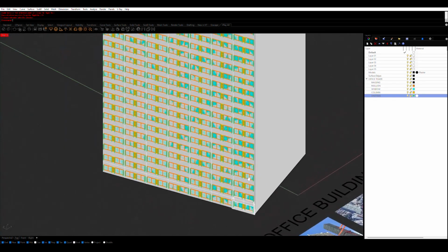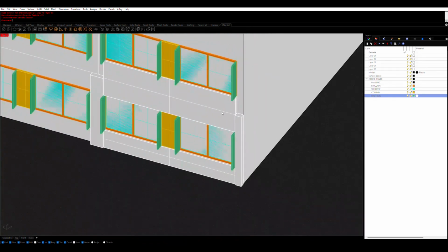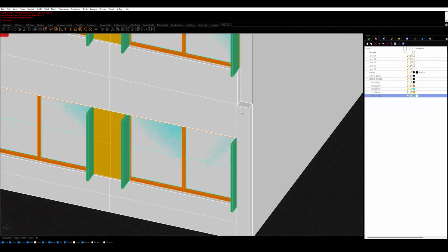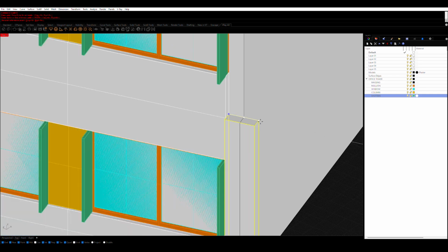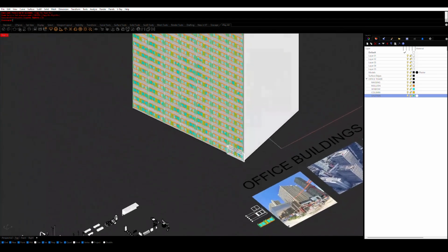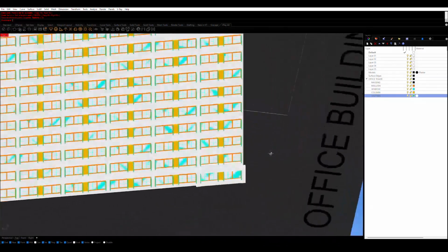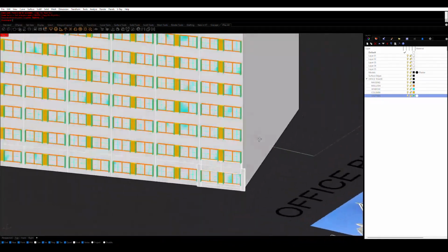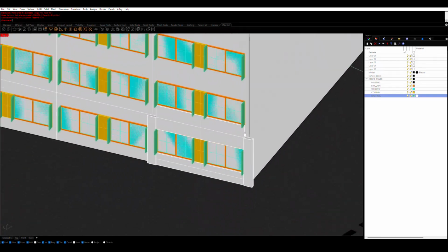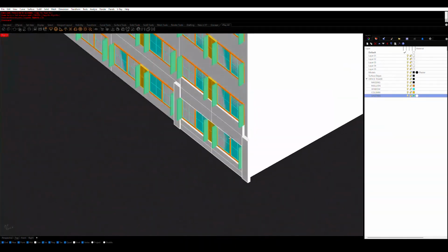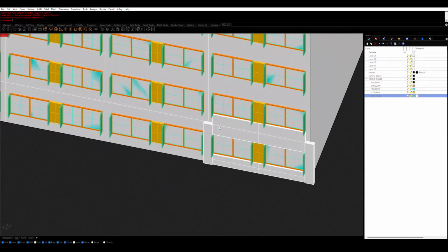Okay. And another issue with our kind of subdivision is that we're going to end up with a half column on the side, and that's just going to result in a slight elongation of our tower. And you could compensate for this in the beginning. I didn't. So just be careful when you're subdividing kind of your buildings, making sure that everything is going to end up fitting along the set footprint that you have.